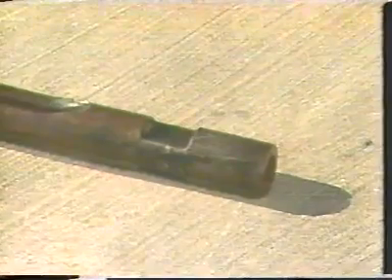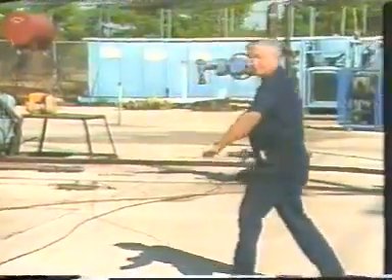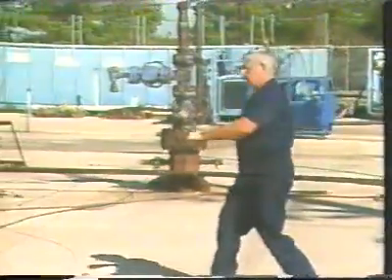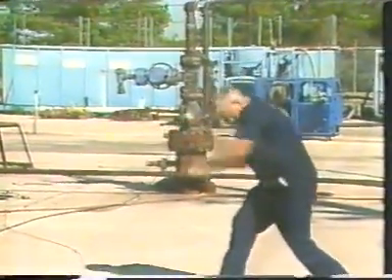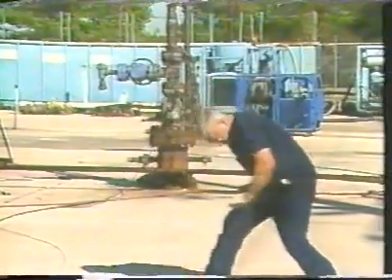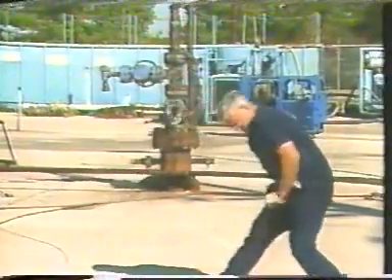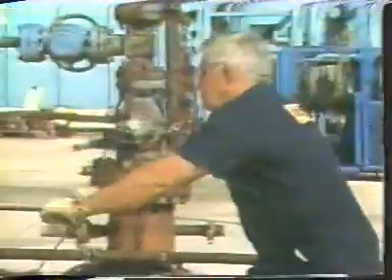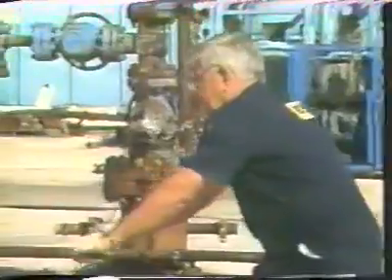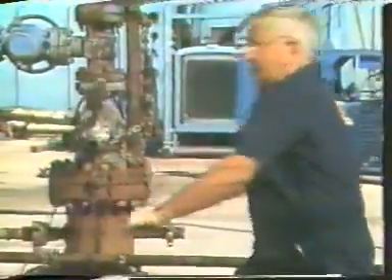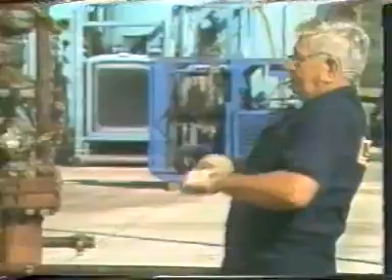To jar up, the tools are gently lowered until the jars are closed. By pulling up rapidly on the wire line, either by hand or with the wireline reel, the tools are moved to the top of the travel of the jars. When the jars open fully, a hammering blow is delivered upward by the jars and stem on tools attached below the jars. To jar down, the tools are gently pulled up until the jars are opened. Then, by releasing the wireline rapidly, the jars are suddenly closed by the weight of the stem falling. This delivers a downward impact to the tools below the jars. In this manner, the wireline specialist can deliver the hammering blows needed to perform wireline operations downhole.